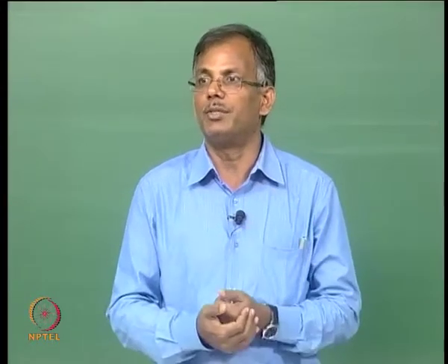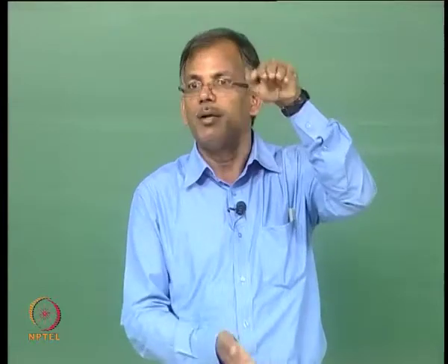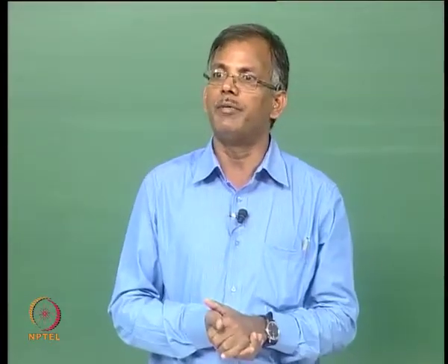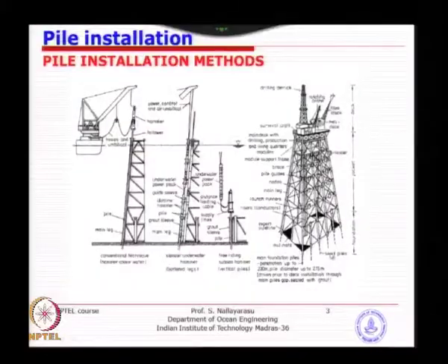The answer will be no, because you have 100 meters of pile going inside the leg, which is almost a waste. Instead, if you go for a skirt pile, you can save all of that. So, that is why in deeper water depth nobody goes for a main pile.